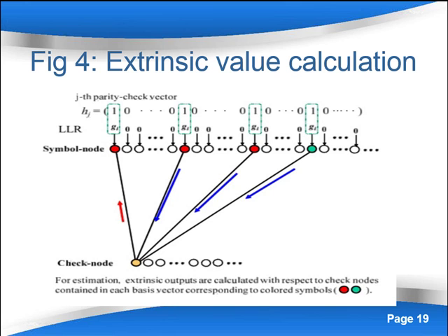After extrinsic values are obtained with single iteration sum product decoding for possible candidate sequences, the average absolute value of these extrinsic outputs is calculated. The SLM sequence with the highest average value of the extrinsic output is selected as the correct phase sequence.